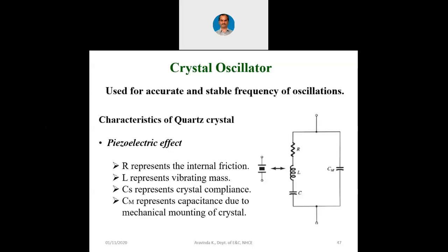So now this crystal has its own natural frequency and it is very much accurate. Accurate in the sense, most of the time the crystal's natural frequency is independent of the atmospheric conditions as well. You already know that the resistors have this positive or negative temperature coefficient of resistance, and capacitors have their own larger tolerance. But the crystals, as they have natural frequency based on their dimensions, can be used in all those applications where timing has to be really very accurate.